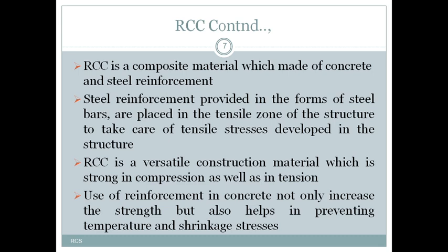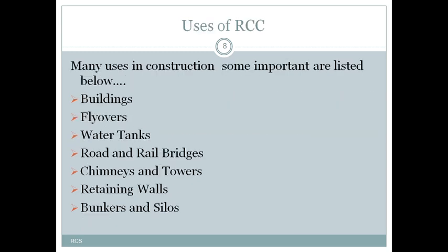Shrinkage stresses occur when freshly mixed concrete dries over time. In that time, the volume of the section reduces; the section shrinks, and then shrinkage stresses are developed. The shrinkage stresses and temperature stresses cause cracks in the member.